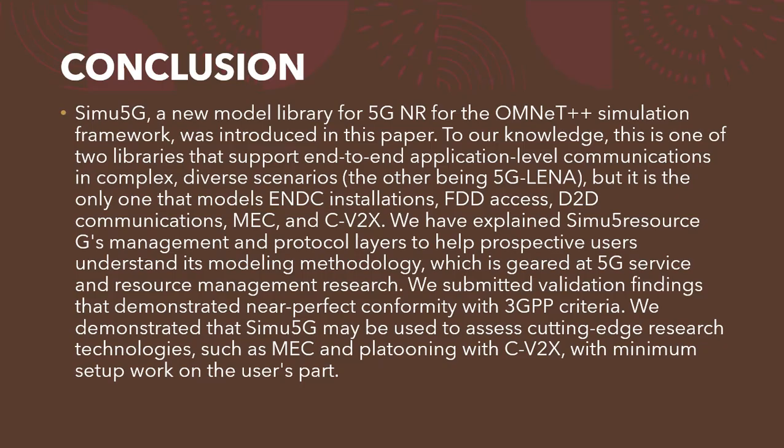Now we have a conclusion here: Simulator 5G, a new model library for the 5G NR OMNeT++ simulation framework, was introduced in this report. To our knowledge, this is one of the two libraries that support end-to-end application level communication in complex diverse scenarios, the other being 5G-air, but it's the only one that models ENDC installations, FDD access, D2D communication, MEC and CV2X.